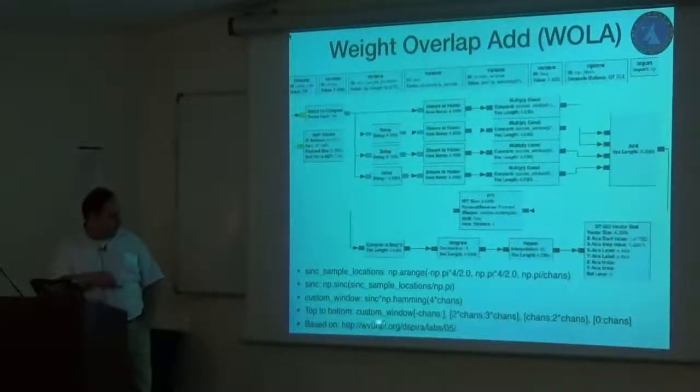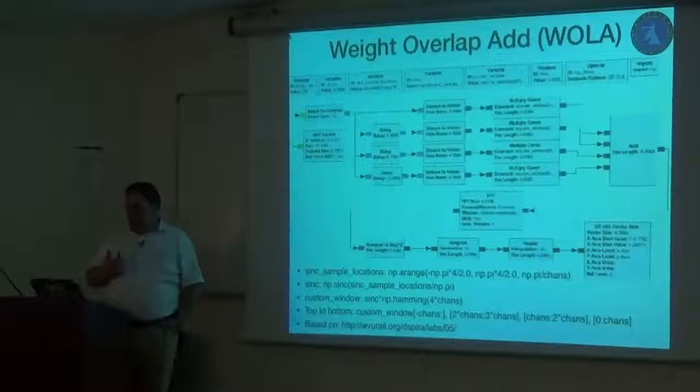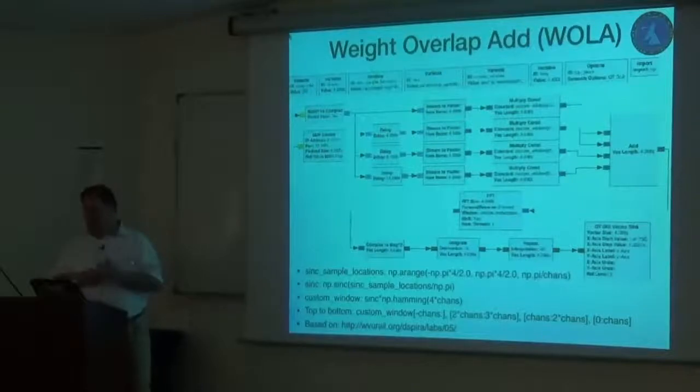And I've based this on this particular website, which is an educational resource for learning how to do radio astronomy with things like GNU Radio. And this is now the thing that we're using at the moment in the Dwingeloo telescope. If we want really high sensitivity, really high accuracy in the power measurements for every bin, then we don't just leave it at 2-second integration.